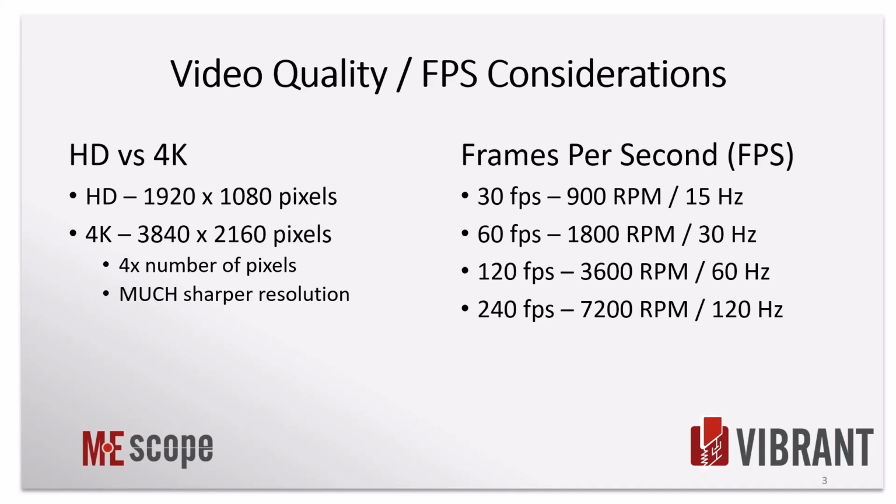Frames per second and how it applies to what you're using. If you're doing 30 FPS and you're using rotating, reciprocating machinery, something where you're looking at RPMs as your benchmark, you're going to get up to 900 RPM of acquired range. And we'll cover it as we get further into it. We have something called unaliasing, where if you are using rotating, reciprocating machinery and you're doing order tracking or multiples of the running speed, you can select the running speed, and then what it does is unwraps the data. So it'll clean it up and it'll identify the different peaks at the multiples of the running speed.